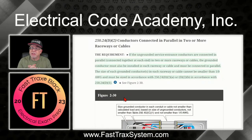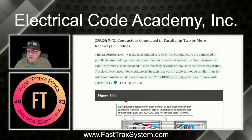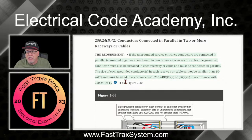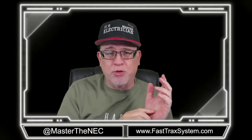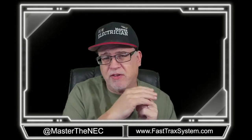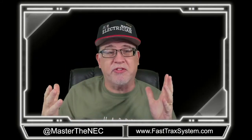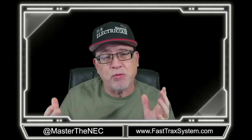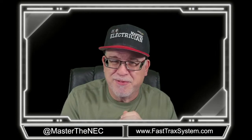Now we're going to talk about these grounded conductors that are installed in parallel raceways, two or more, and how you would size those. All right, so now we're in 250.24(D)(2). But guess what? I said this was going to be a two-part series, but I decided to make it a three-part series because I think it's important to understand what you do when it's parallel sets and when they're done in separate raceways, what you have to do with that. So stay tuned for part 3.